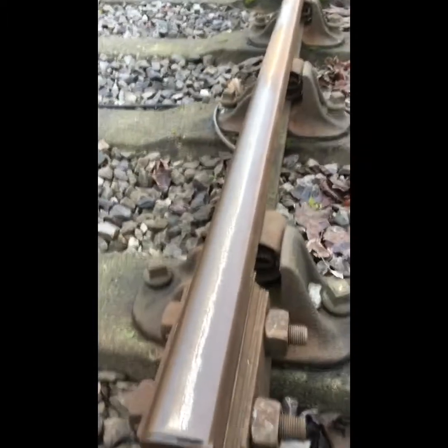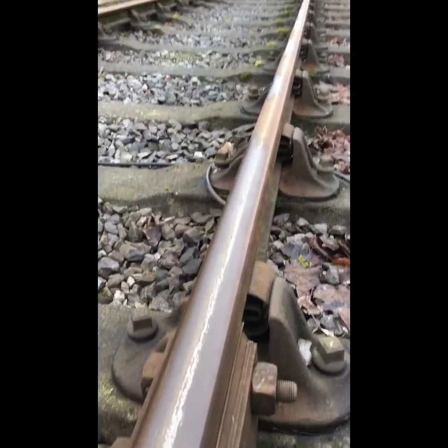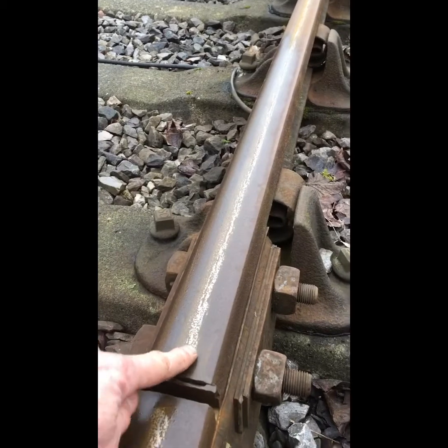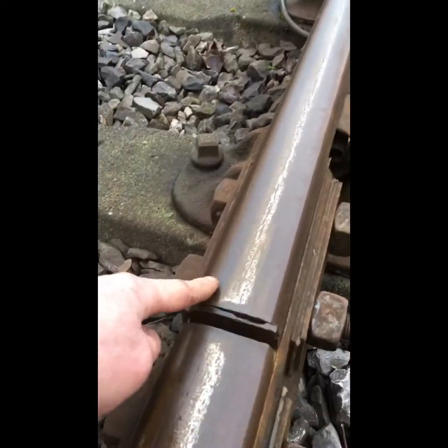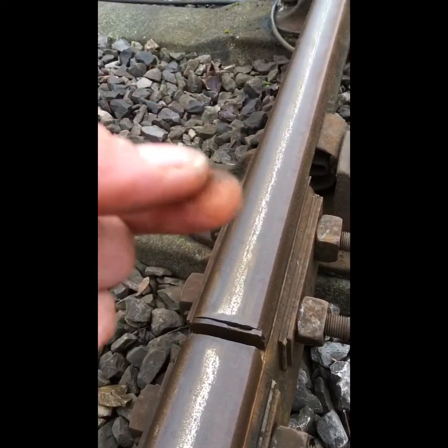Another thing you can talk about on track circuits is quite important. Obviously in 2020, not many trains are run on heritage railways, so you have a lot of rusty railhead conditions. You can see here where the wheel of the train has been clearing the railhead, and the rest of it is still entirely rusty, and you can end up with a lot of rust contamination.